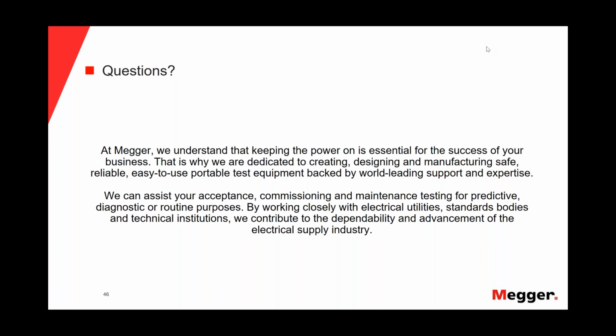Well, keep in mind that we apply the voltage for the PD test between the center conductor and the concentric. So we are looking mainly for issues in the insulation of the cable or the splices and the terminations. So problems in the jacket of the cable will be quite difficult to detect with partial discharge. At least that damage will be related with other damage.